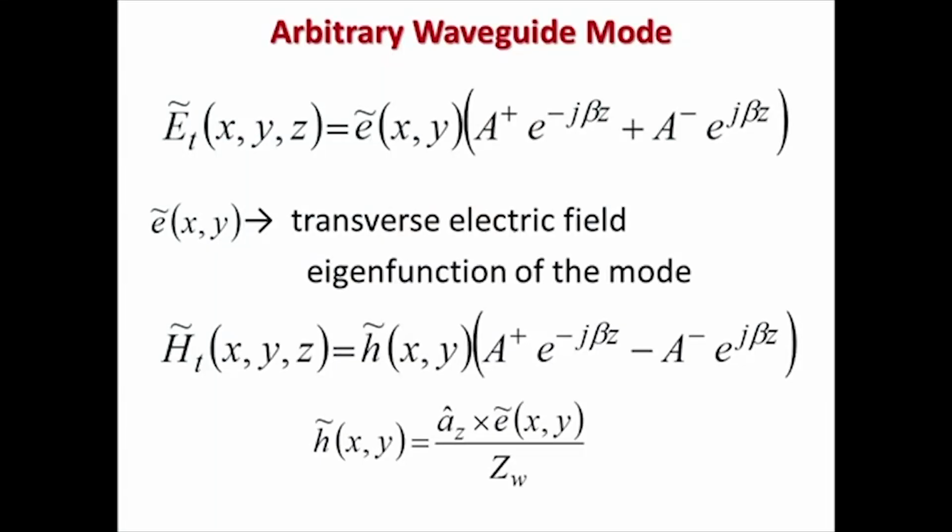So, if this is done, then at a terminal plane we can uniquely define voltage and current. Obviously, voltage and current will propagate in the z direction in the form of a wave, but the terminal voltage and current, they will be unique.